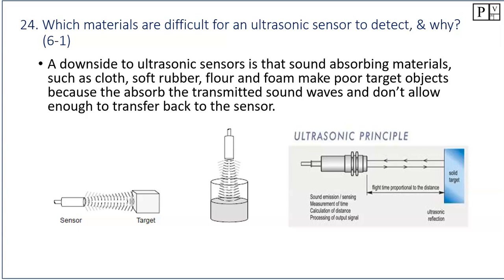If you have a froth on the top or bubbles on the top of the liquid level there, then you would use the one that goes at a different frequency. You use a radar sensor instead of an ultrasonic sensor. So anything that absorbs sound waves would not be a good application for an ultrasonic sensor.